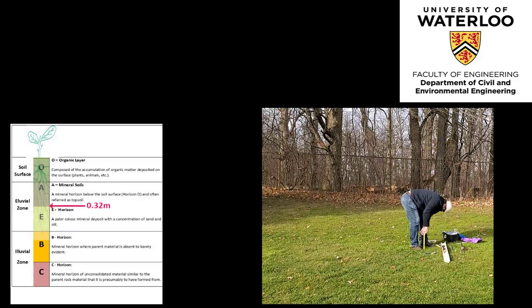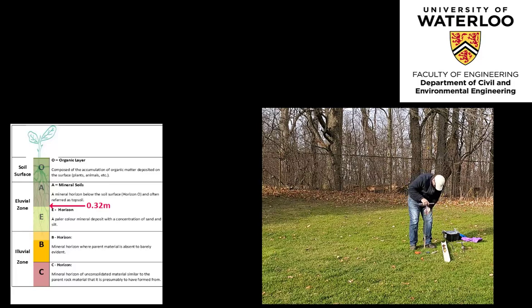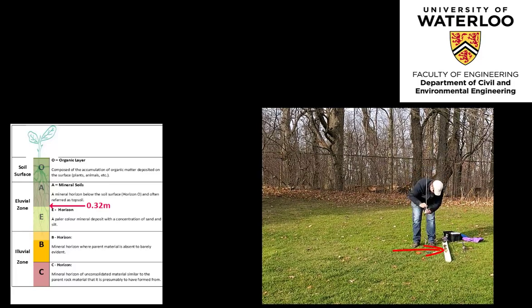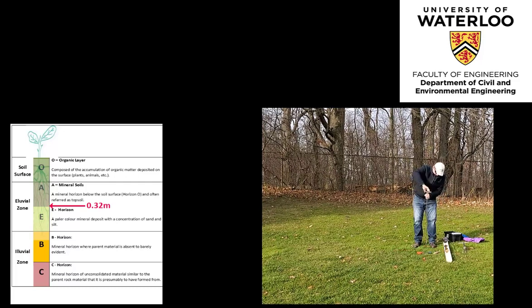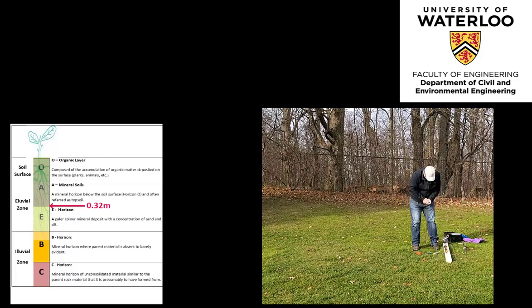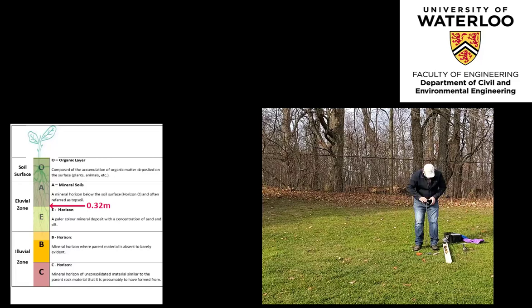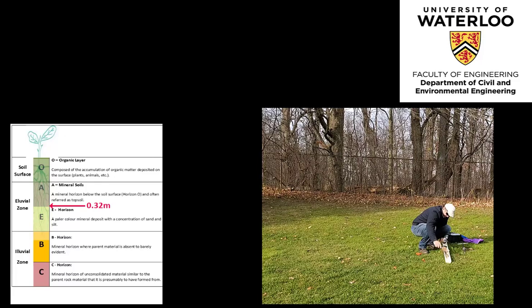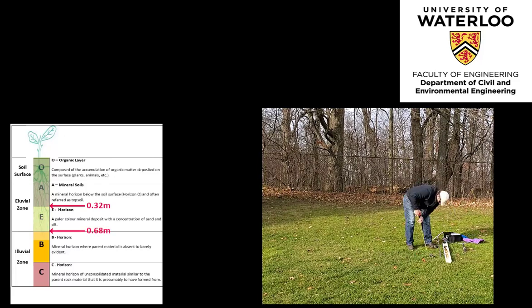It is here noted that not all soils exhibit an E horizon. For this particular core, the lighter colored material, which is non-consolidated in nature, is identified as the E horizon. A third auger core was advanced between 52 and 70 centimeters below ground surface, which was the maximum distance the core could be physically advanced without mechanical means, such as a drill rig. The E horizon material was present to a depth of 68 centimeters below ground surface, and then presumably the B horizon began, which was composed of a highly cohesive clay till material to a maximum depth core of 70 centimeters.